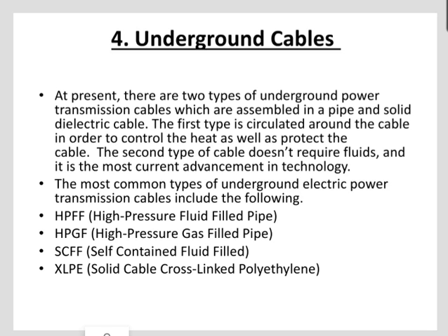The underground electric transmission cables have low visibility and are not affected by bad weather, but the cost of this cable is high. The finding of a fault in an underground transmission line takes much time for repairing as well as locating. This one is a disadvantage. So in urban areas, this type of transmission is enclosed, shielded with dielectric liquid and a metal pipe that is either fixed or sprayed through pumps.